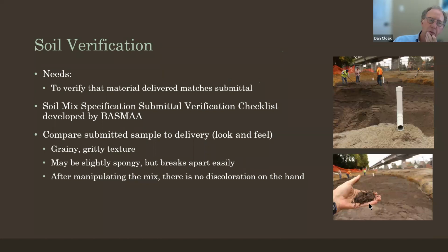Because you have plants, you have earthworms and bugs in here, and the idea is you want this very dead soil as it's installed to turn into a living soil, both because that gives you better pollutant removal, more ways of processing pollutants and of fixing them to soil particles, but also over time, all that biological activity gives this tilth and keeps the soils open.